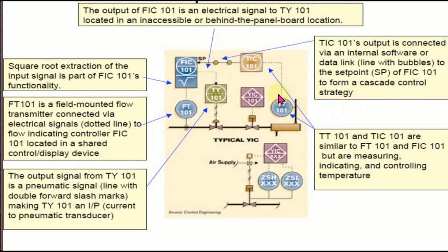So the TT101 here and TIC101 here are similar to FT101 and FIC101 but are measuring, indicating, and controlling temperature. So this one here is the air supply.